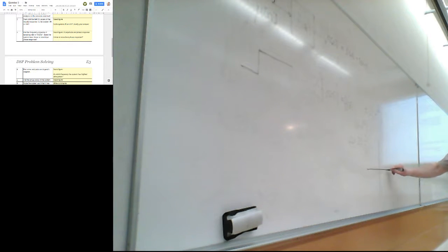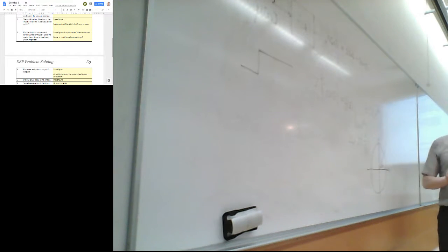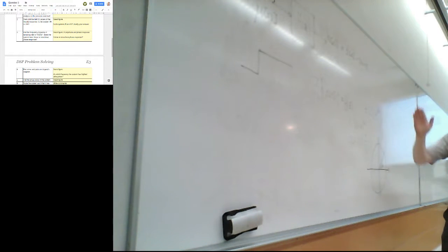Oh, much better. So on the unit circle, in the complex plane, angle omega is right there. And that point here, e to j omega, is basically here. Like that. Good. So basically, the frequency response is the same as you evaluate the transfer function on the unit circle.